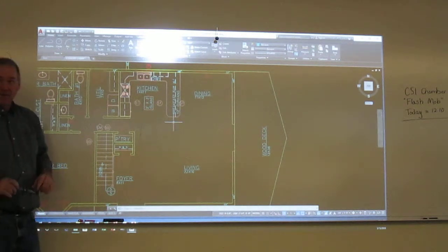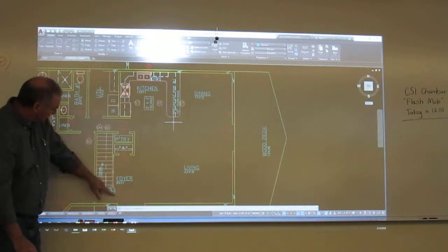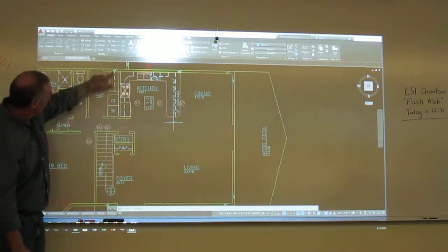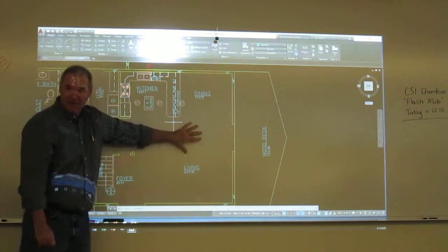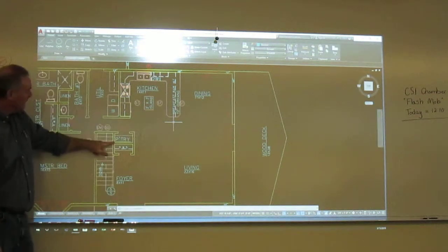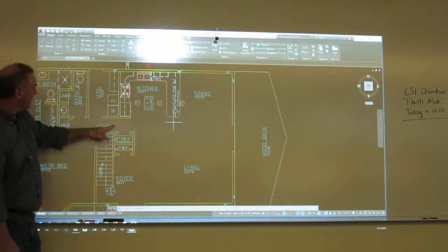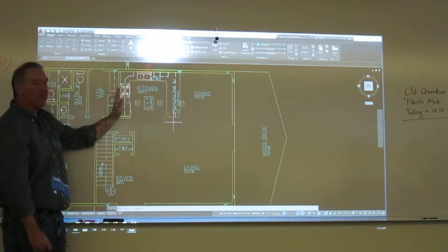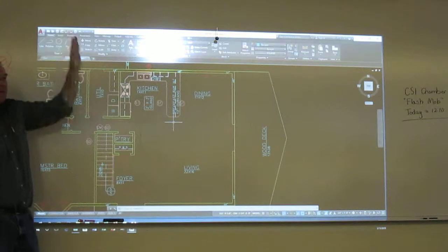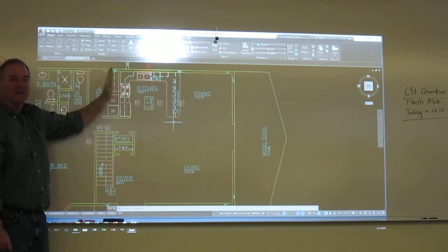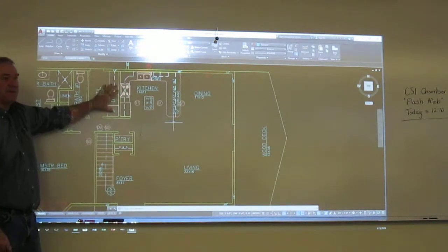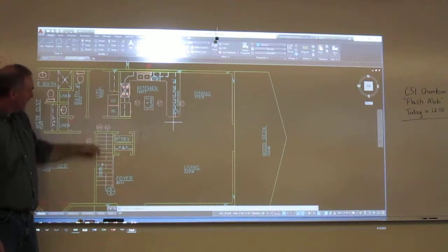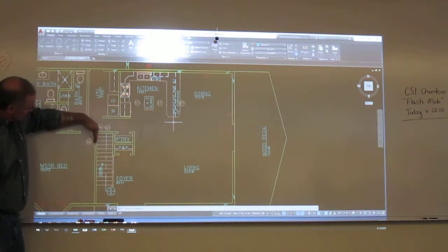Now the other thing I can do is I can run my scissor truss all the way here. That's going to vault all this stuff. And then I can expect my framers to come back in and fill this section in. Because they're building this wall, so we can just carry that all the way up and they'll never know that that truss isn't a flat truss. Okay, you just overbuild inside. So in my mind, this is going to be flat.